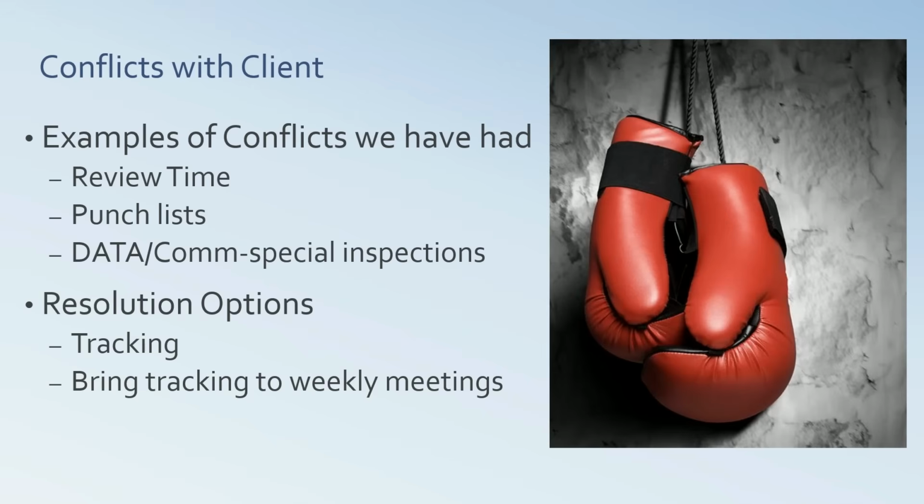Now, your project manager ultimately will decide when they want to fight that fight. Your job as a QC manager is to not let anything collect dust on your desk. You have to tackle things timely, and in the right order. Big stones, small stones, right? Make sure things that hold up schedules, such as RFIs and submittals, are reviewed timely. If you've got an end user or a client that is taking more than their review time, your job is to provide that information to your project management team, whether that's a construction manager, a project manager, or an owner if you're a smaller outfit. And then they're going to choose when they play that card.